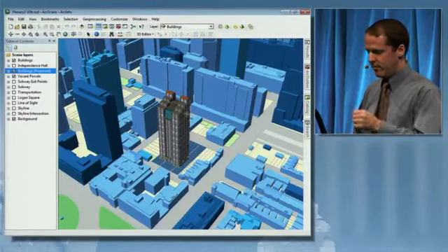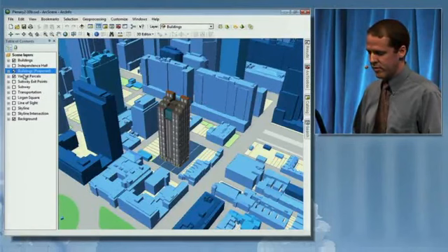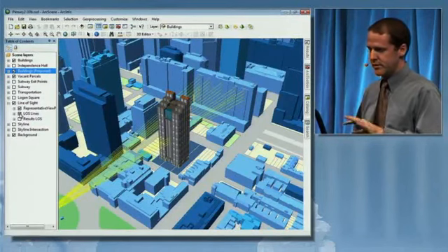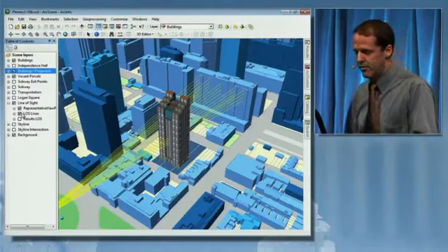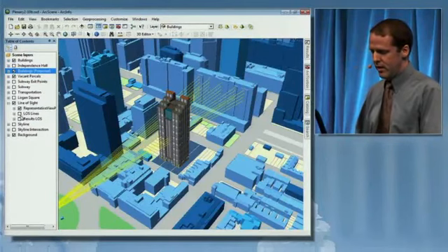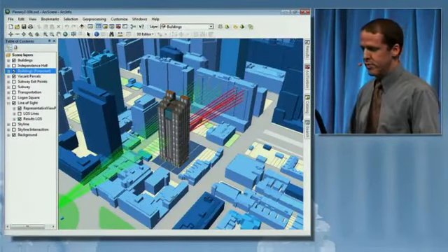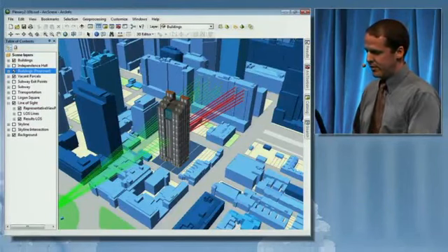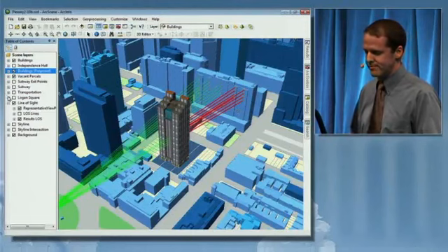Now, more than likely, this new building will block the view of Logan Square for several apartments in the neighborhood. So we want to perform a quick line of sight analysis to determine exactly which apartments will have their views blocked. New at 10 is the ability to use multi-patch features in that analysis. And so we've highlighted in red those apartments who will have their views blocked.